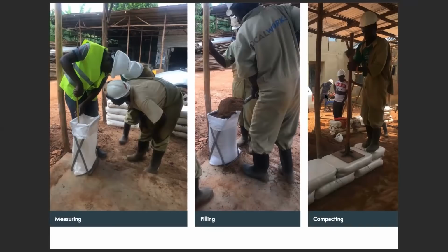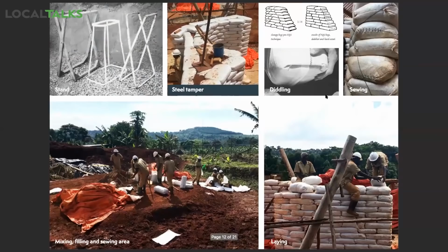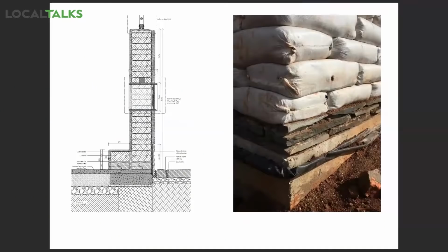Someone asks to speak about termite proofing. Well, the termite proofing here is ensured by using bags, I guess. Some tests have been done. We haven't done them ourselves, but from the research we have read, if you put a piece of wood in this bag next to another piece of wood in the open, the other piece of wood will be eaten immediately, and the termites will not bore through these bags.